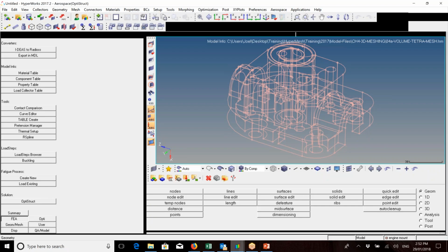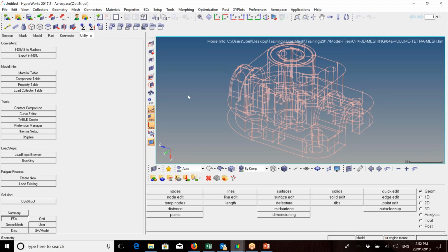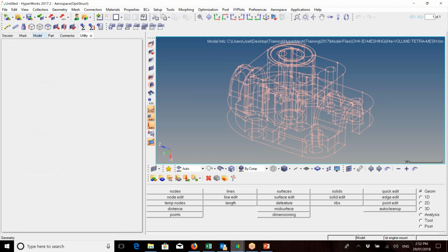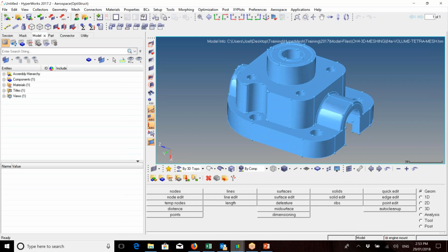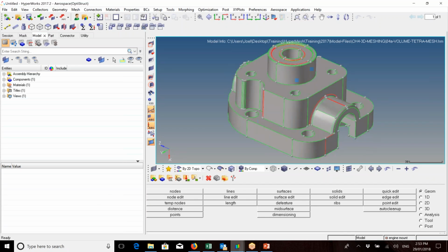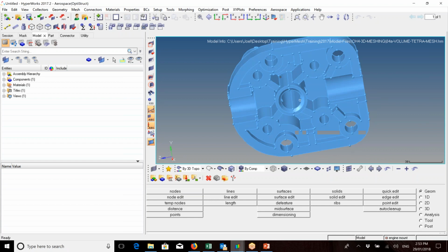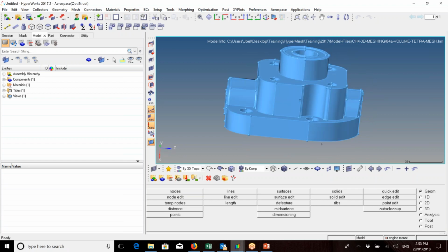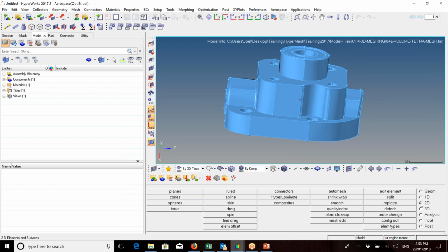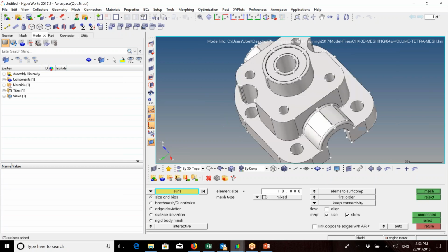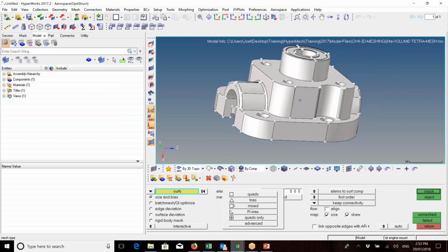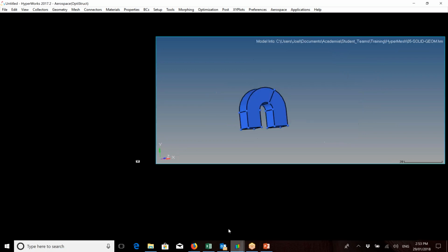what we're going to do now is a very quick overview of your 3D meshing. So this is a solid, to make sure. 3D, oh, it's not, sorry. It's a 2D, that's all right though. Now I'll just explain how I would mesh this. With your 2D section now, you want to do tetra meshes with your volume mesh on something like this. You do your auto mesh tool, select all your surfaces, because this could take a while to mesh. Change this to your tries, and then you'd mesh it like that. But I will show that on this section here.